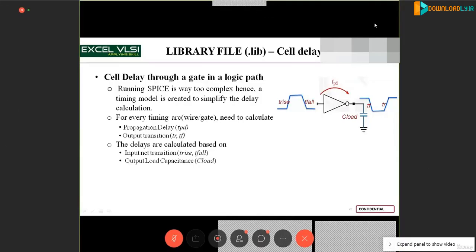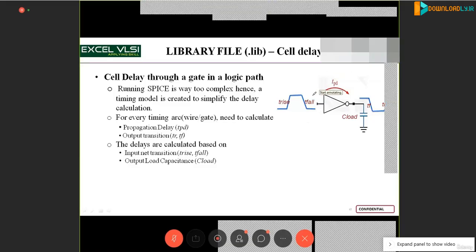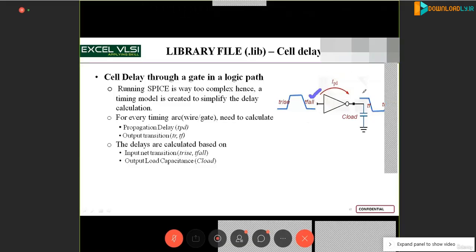Once an input is given at the input pin, the time it takes to travel to the output is called propagation delay. That delay value is calculated using the timing models we discussed previously, that is, non-linear, linear, and CCS timing.